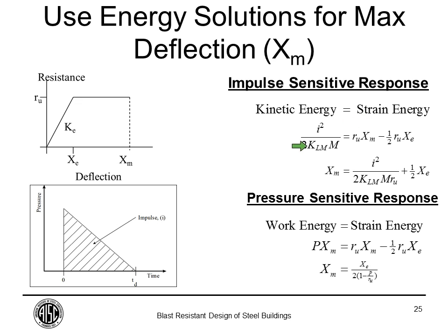In other words, the energy of the blast load could be coming from the total energy under the blast load, which is the impulse, and then the strain energy in the member is calculated by taking the area under the resistance function. So if you have a component that is in the impulsive region, meaning your load duration is so small compared to the natural period of the member, then you use the kinetic energy of the blast load, which is the impulse, and you equate that to the strain energy of the member,